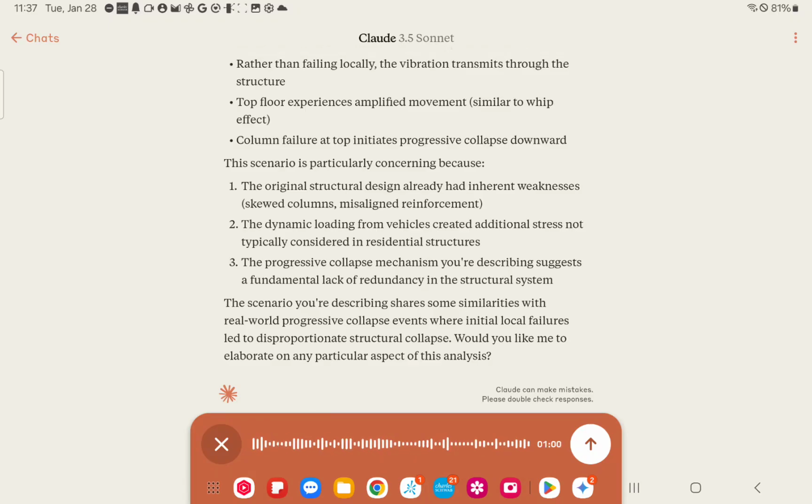collapse location. I call it a butterfly failure because it's approximately the middle span of the two column supports. When this building was originally built, they had to repair cracks that presented as going down the entire pool deck, approximately mid-span of this 21-foot span, on the underside of it.